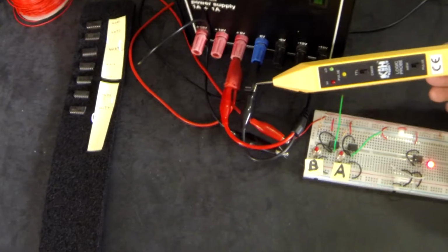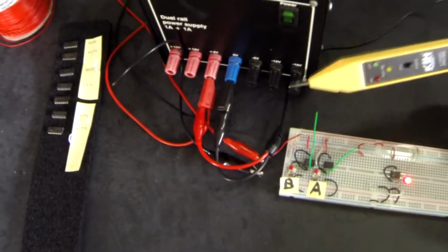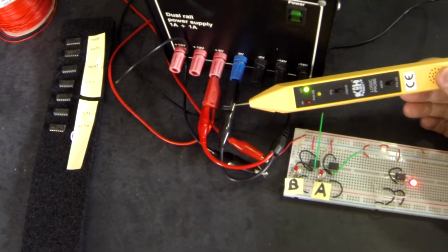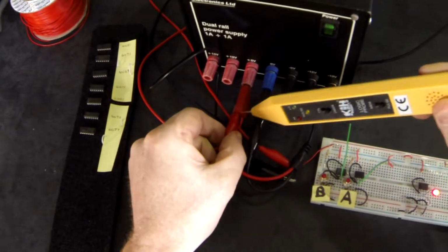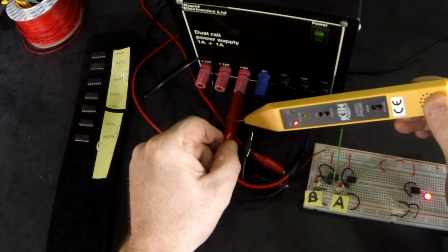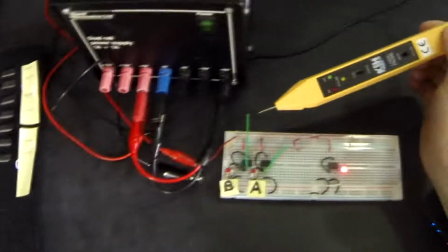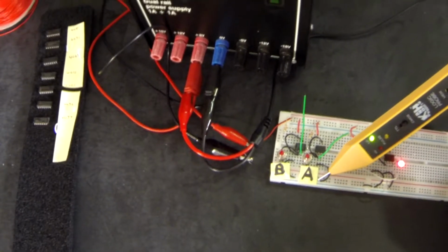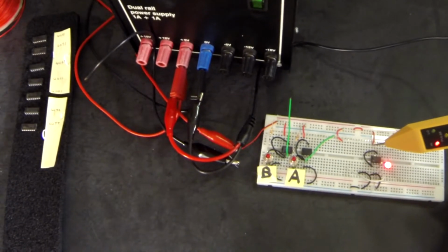So if we go to our power supply, and I've connected up my logic probe to my power supply, and that needs to be connected to the one that you're using to supply the voltage for your circuit. You can't do it separately. When I connect it to 0 volts, it will go low and the green LED comes on. And when I connect it to high, the red LED comes on. It's a good way of checking whether you've got power going to a circuit. So if I connect it to my power, high, connect it to my 0 volts, low, and I can check anywhere in the circuit to see whether I've got power going to wherever I need to.